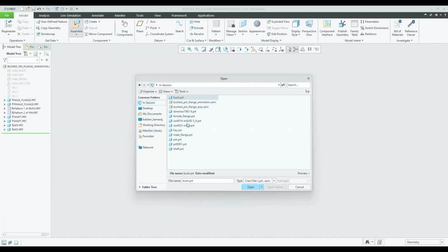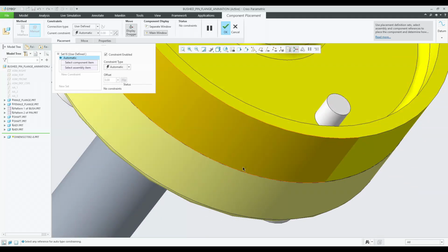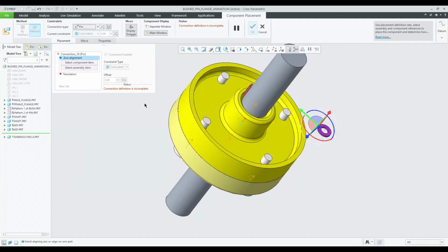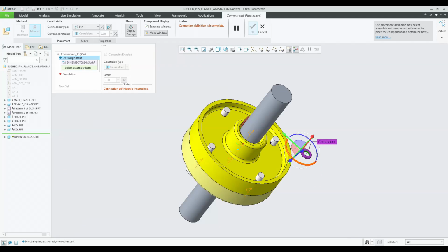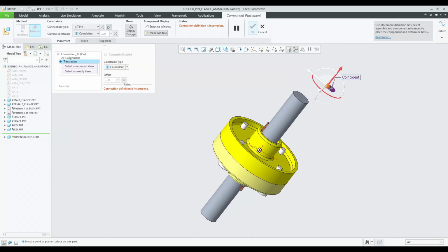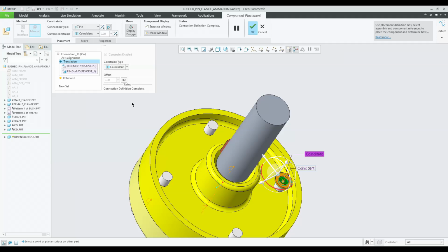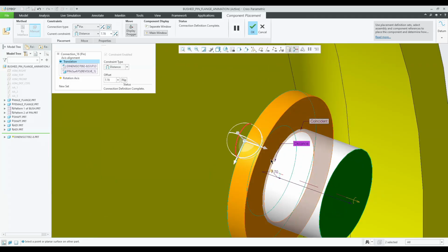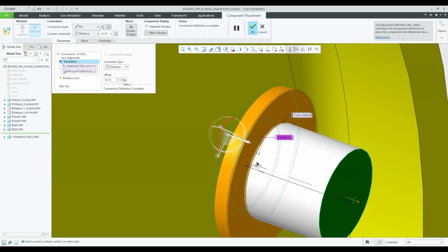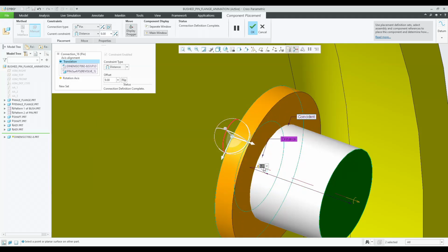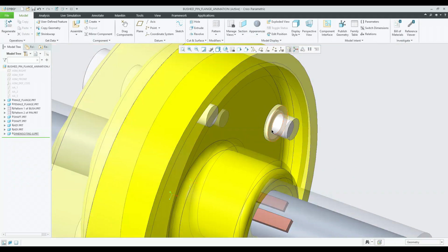For the washers and the nuts also I'm going to use washers as this one. This also will be considered as a pin connection from here to here, and the translation movement as surface to surface will be in the distance, as 9 mm. So one washer has been assembled.